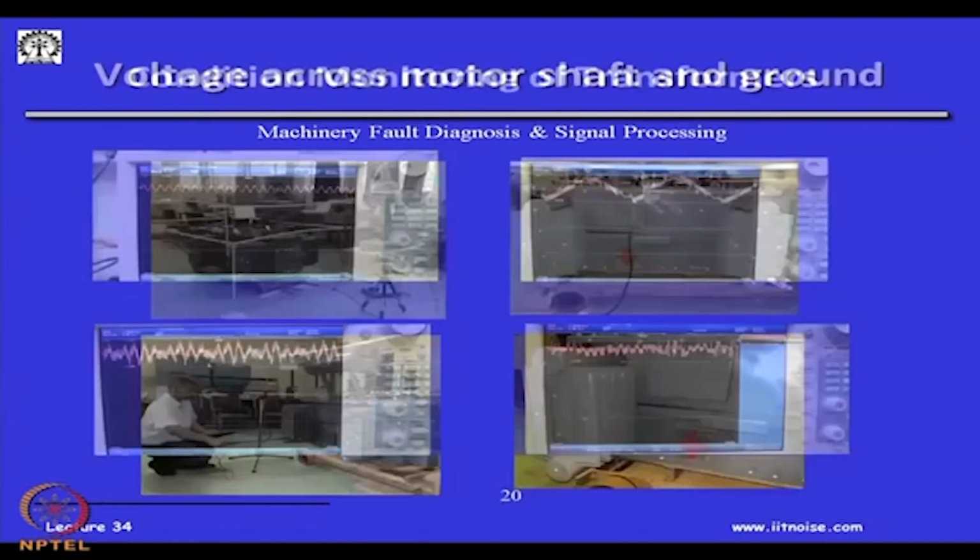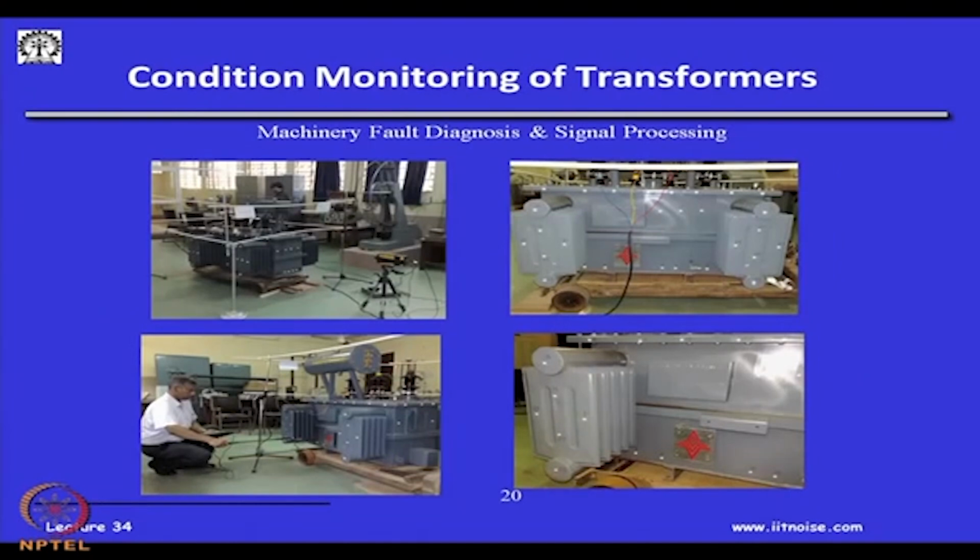though you can also do vibration monitoring of electrical motors. And then how do you monitor the condition of transformers? Basically, you would have seen a transformer is essentially nothing but a core of coil, and this coil is kept in a tank full of oil, and this oil is to be maintained at a particular height, and because of the eddy current losses, etc., this current generates heat that has to be dissipated, and that is why there are fins. You will have seen in many transformers there are tubings, etc., which carry nothing but oil, and this is a tank wherein oil is there.